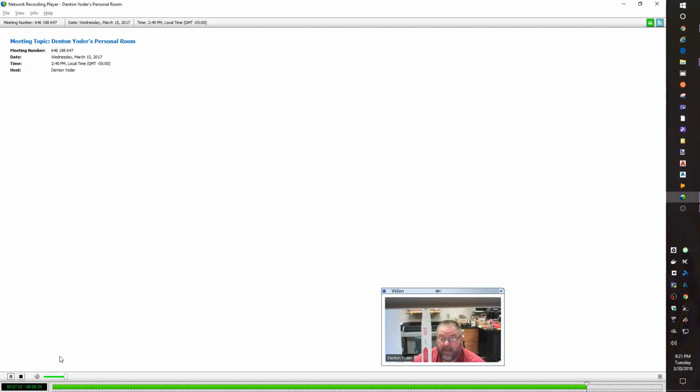Oh, let me add one more. We are recording from the first point we selected plus the reading we got to make our height of instrument. All the rest of the readings we will subtract from that height of instrument to get the readings for those locations.